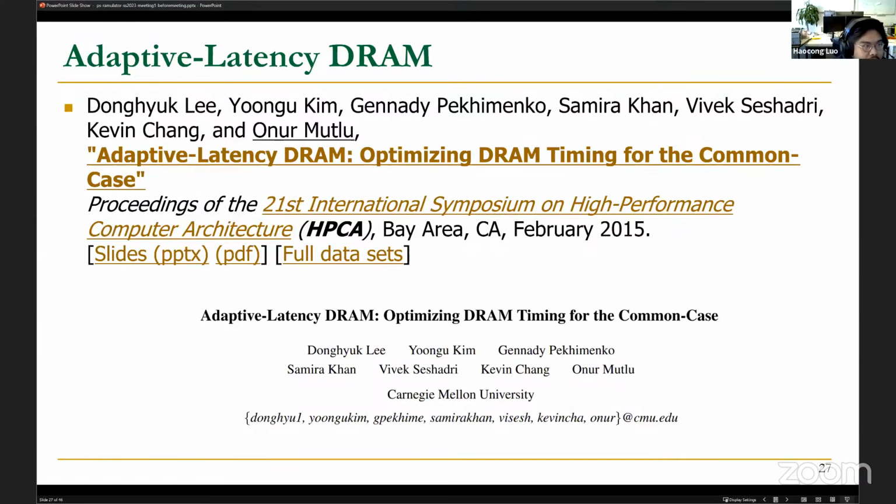Let's say for this Adaptive-Latency DRAM paper, we find that in moderate operating conditions, let's say room temperature and enough power supply, we can safely operate modern off-the-shelf DRAM modules with much reduced access timing parameters.